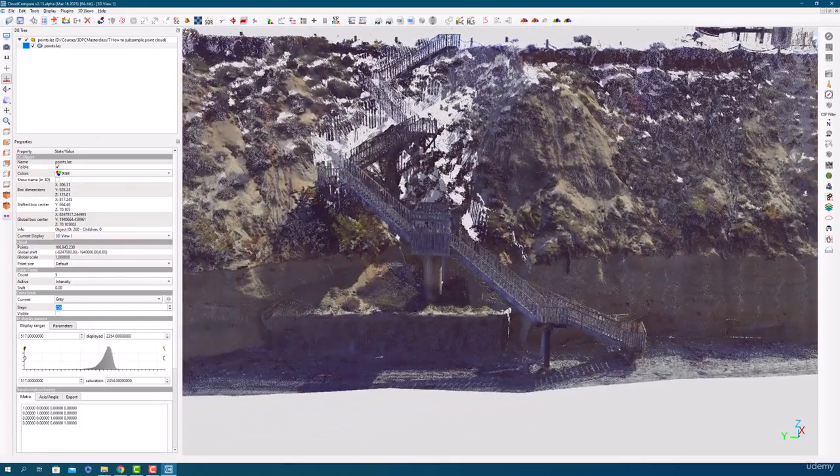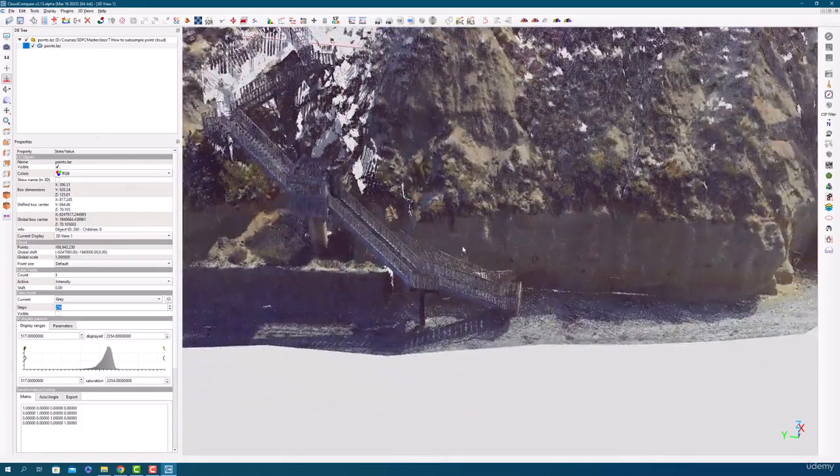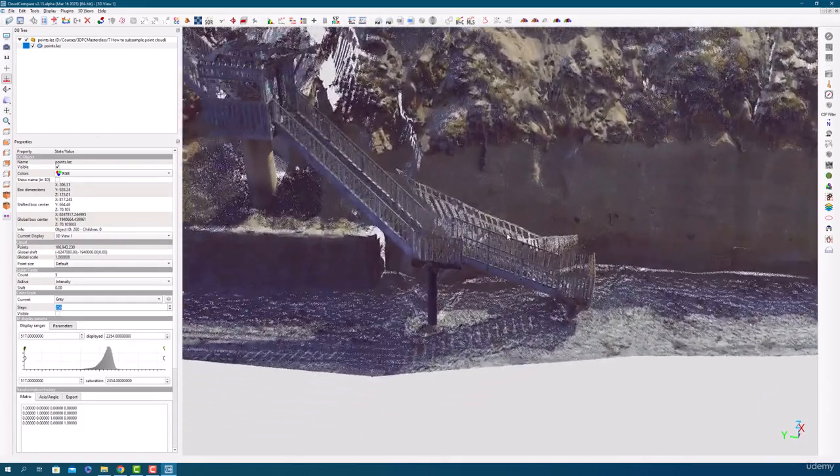Using point cloud subsampling, you can reduce the number of points in the point cloud while still preserving the essential features and characteristics of the landscape. The resulting subsampled point cloud would contain fewer points and occupy less memory and storage space, making it easier to process and visualize. However, the subsampled point cloud would still retain the critical information necessary for the task at hand, allowing you to perform your analysis or measurement accurately and efficiently.